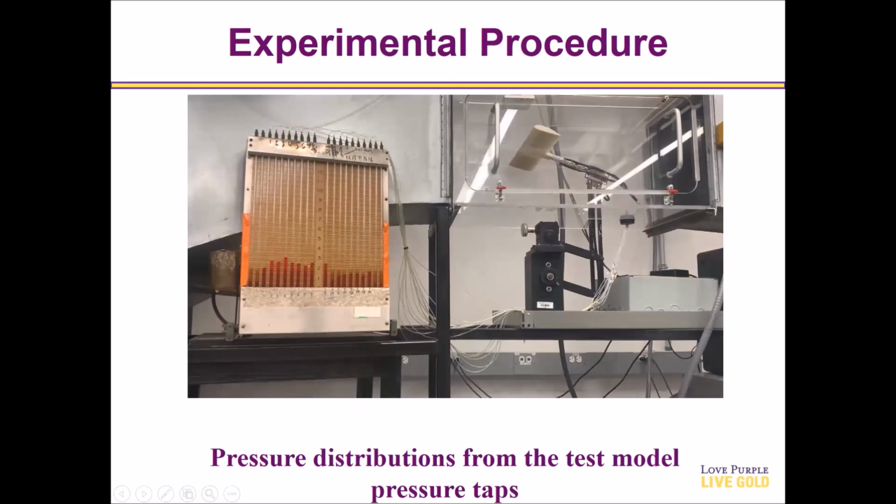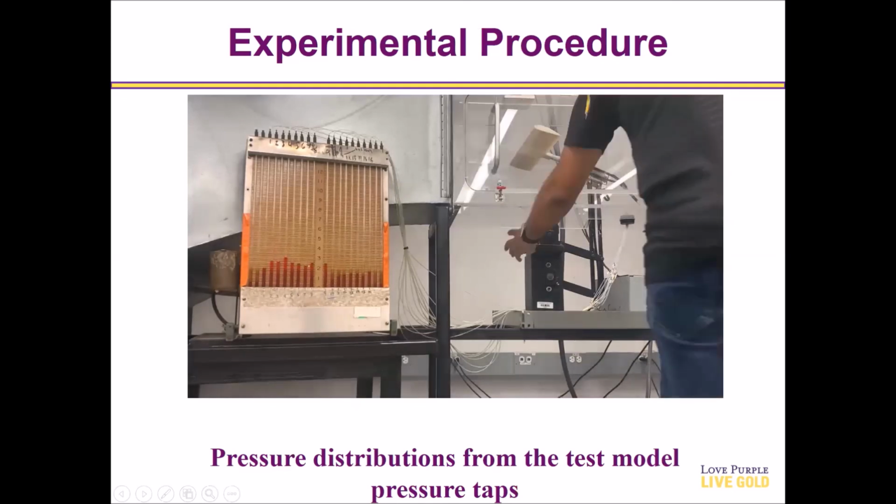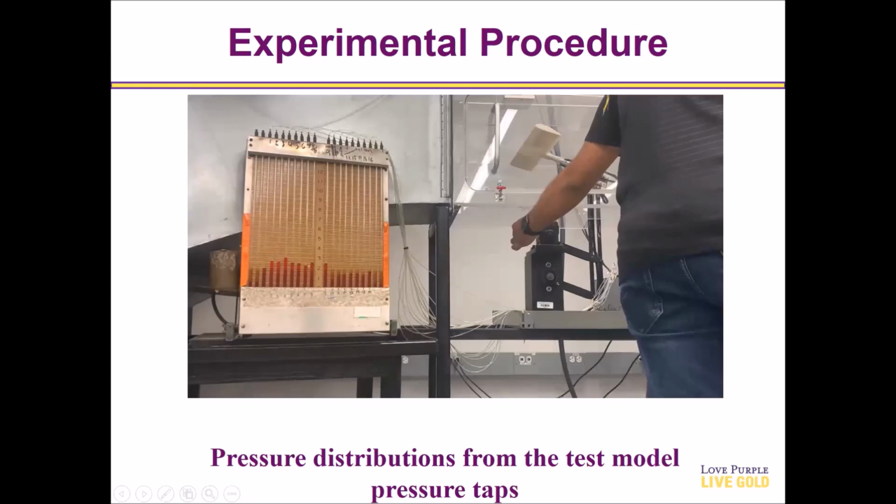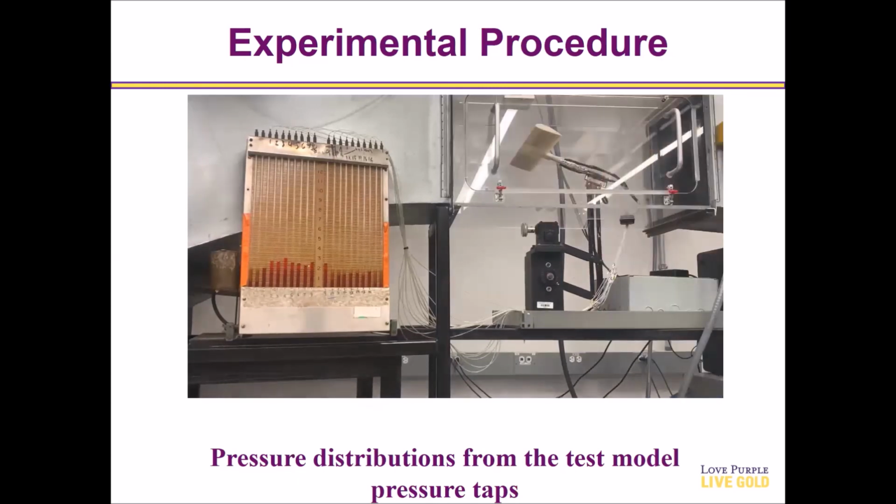However, your data will have an observed stall angle, which can also be verified by plotting the lift coefficients against the angle of attack, where you would observe a decreasing trend at and after stall. You will be given the pressure data for this experiment. Use the pressure data to evaluate the lift and drag force along the airfoil, plot the respective lift and drag coefficients, and determine the stall angle for this particular airfoil.